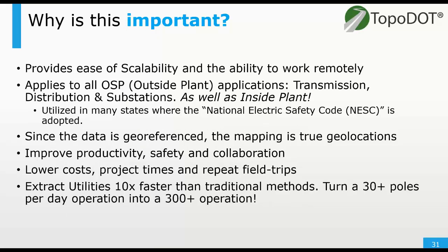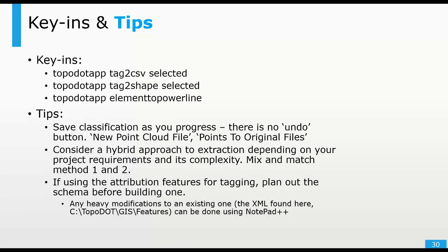Mike, I had a couple of tips while you were doing your examples. I wanted to mention that if you're planning to do any encroachment or classification or clearances of your wires, the wires you've created, make sure you don't modify them, for example by joining all the wires together into a line string, or faceting these lines into a line string, because then you modify the actual information on the wire.